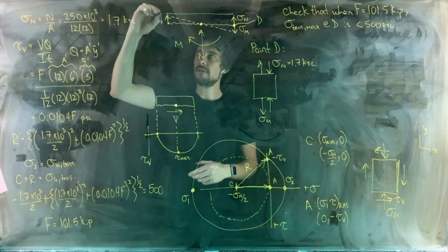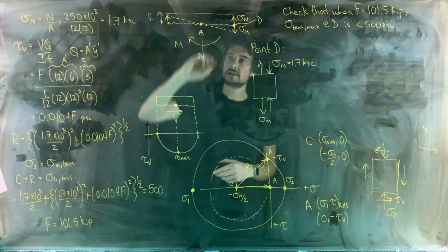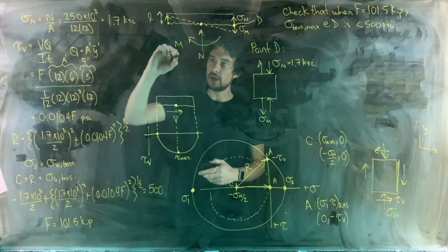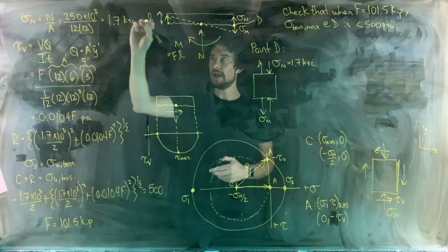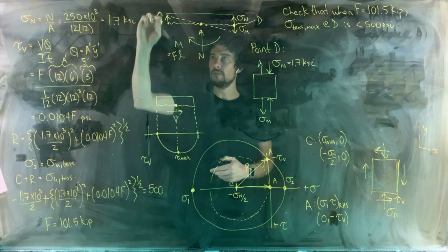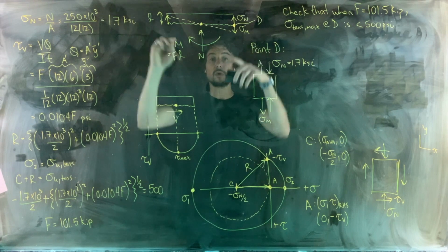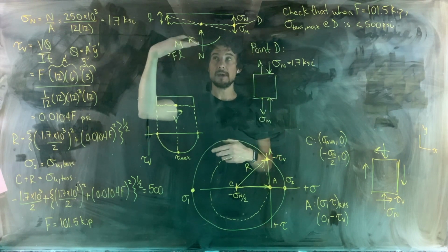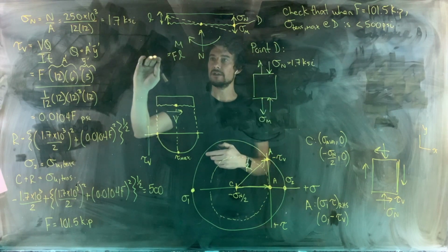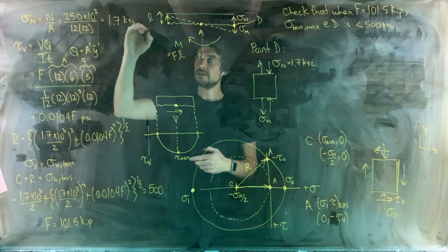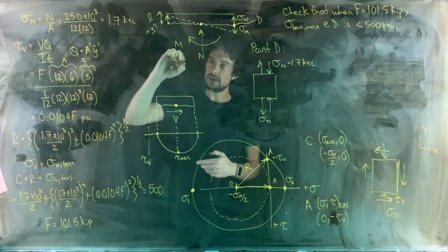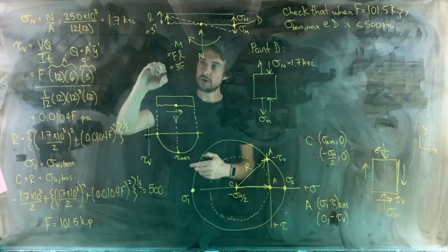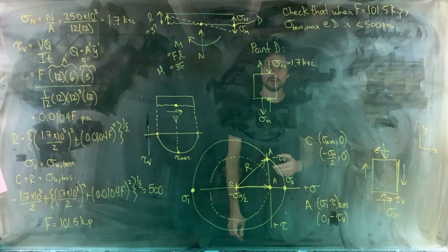Now, we said that the moment will be our value of F times L. That moment will be greatest when L is the full 3 inches. So when we're looking at the portion of the concrete pad that is directly contacting the ground, right? So we'll let L equal our 3 inches, which means that this is 3F for our moment, okay?